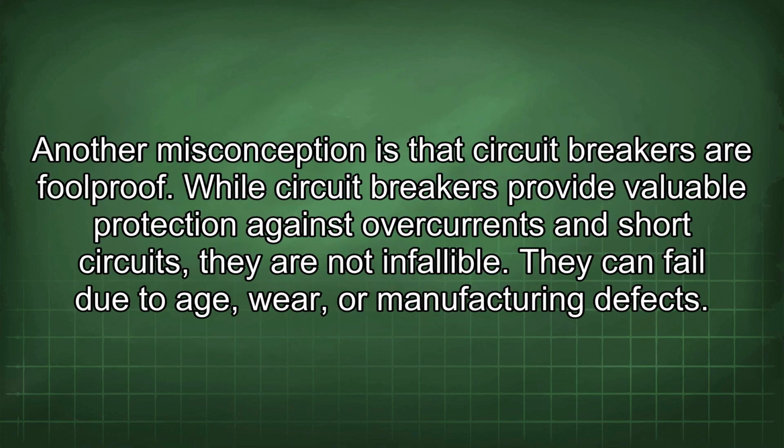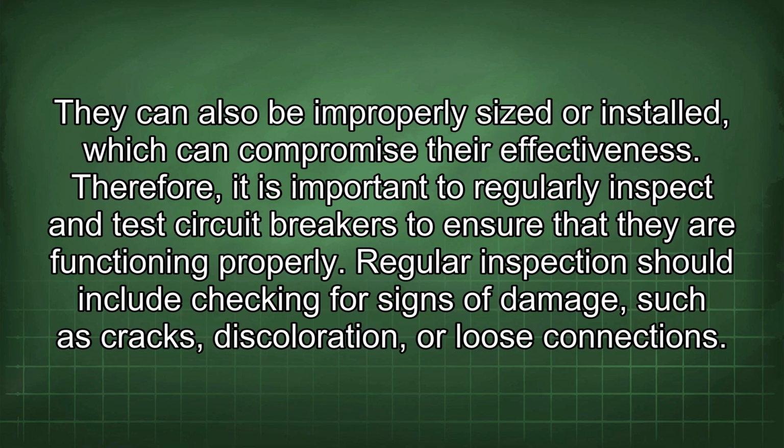Another misconception is that circuit breakers are foolproof. While circuit breakers provide valuable protection against overcurrents and short circuits, they are not infallible. They can fail due to age, wear, or manufacturing defects. They can also be improperly sized or installed, which can compromise their effectiveness. Therefore, it is important to regularly inspect and test circuit breakers to ensure that they are functioning properly.